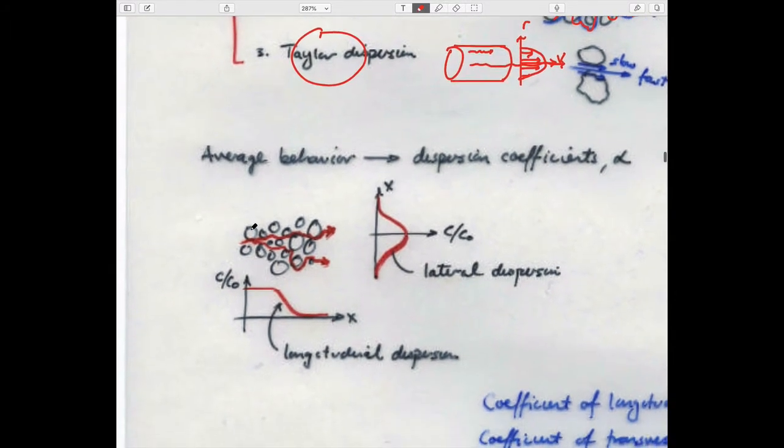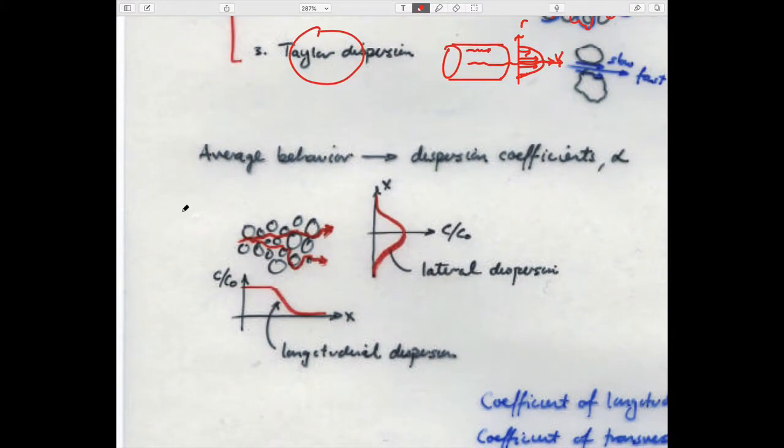And it just explains this idea of, as you go downstream, and you start off with this distribution that looks like Manhattan, concentration versus radius, then it takes on two forms. If you draw a cross-section across here and look at it, this would be the distribution of concentrations because of this lateral spreading.